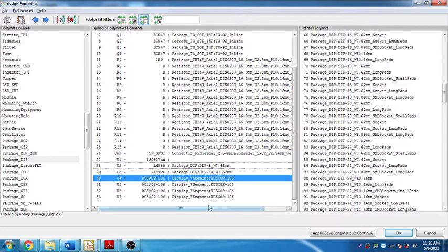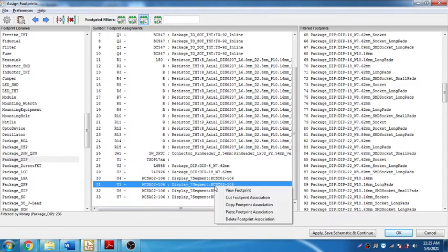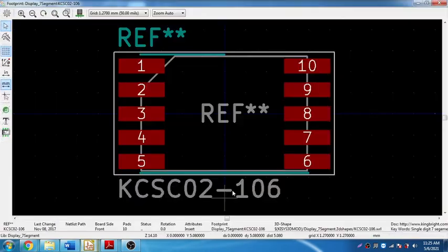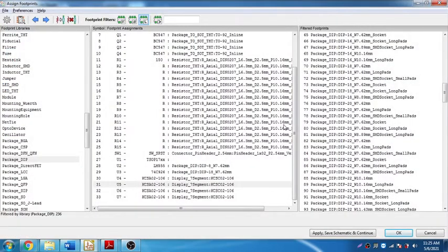That's it. I think for the 7 segment display, you see here already a footprint is assigned. That's something very good. We have, oh, that's SMD actually. This is assigned for the SMD, but we are not looking for an SMD. We are looking for a through hole actually. So we need to change this as well. So what I suggest is, let me go through this particular thing.